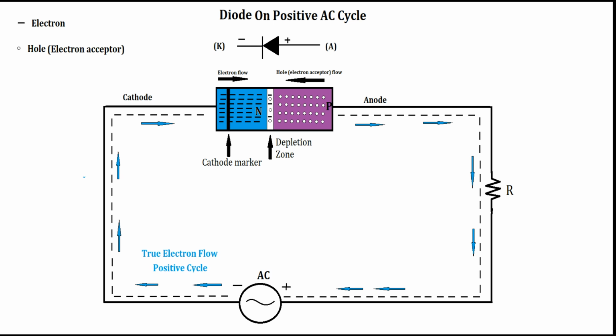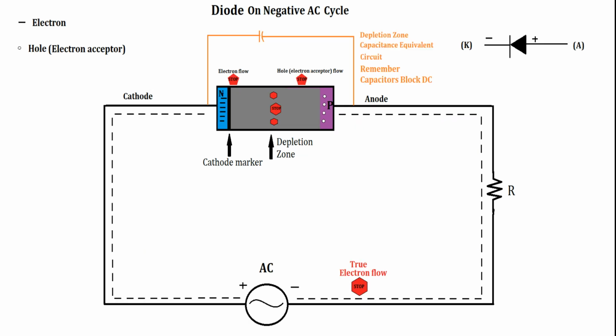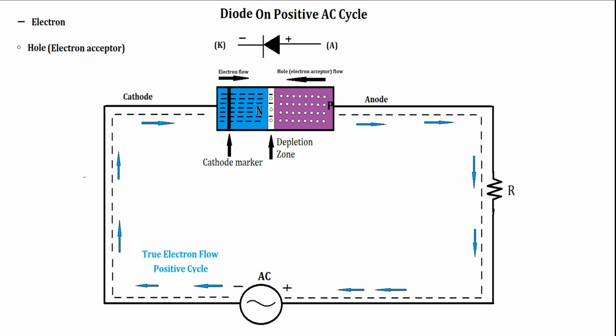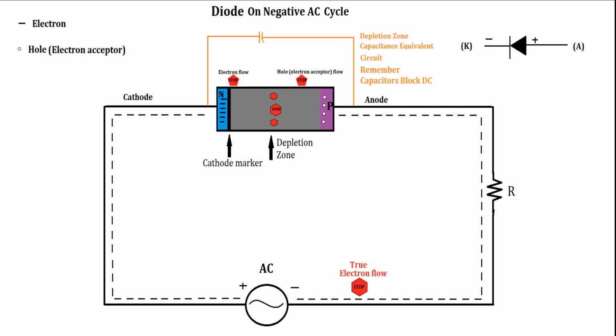Notice the schematic symbol's polarity on the diode matches the AC supply's schematic polarity. This is forward biased, so the current flows. We're back to another switch. Remember, AC goes forward and then backward, positive and negative. So when the current flows back, or negative, we have a situation that looks just like the reverse bias on the DC circuit. So no current is flowing.